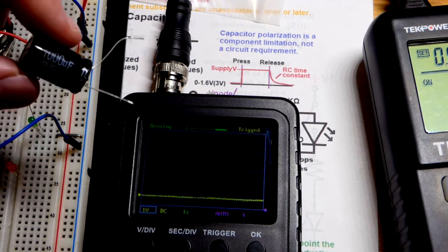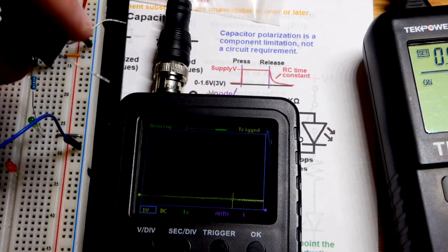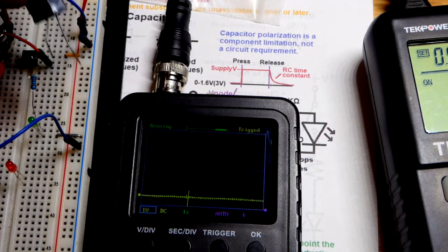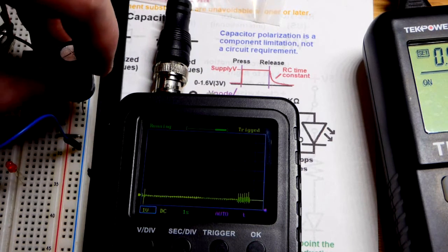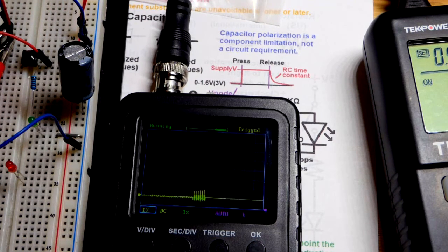If you are not sure how charged they are, use a resistor to discharge them. And if they have a high voltage or something, use a resistor that can handle the current to slow down how fast it discharges so it's not instant. But in any case, that will prevent a big pop or whatever, electrical spark.